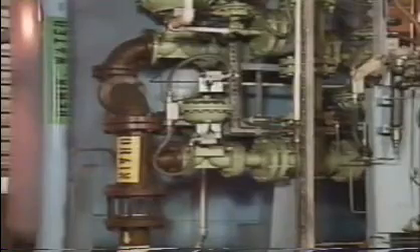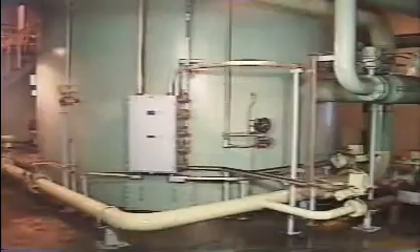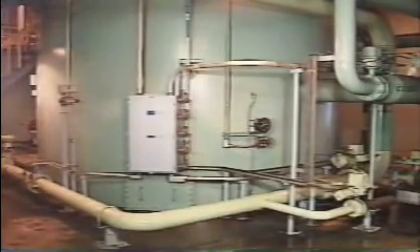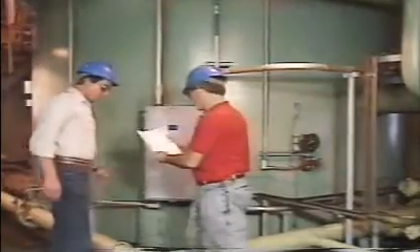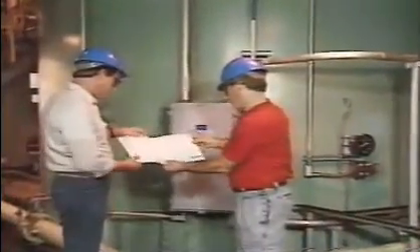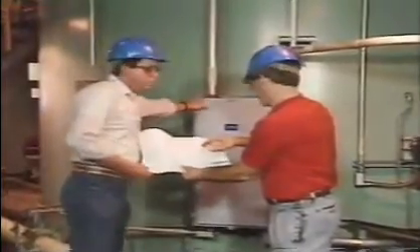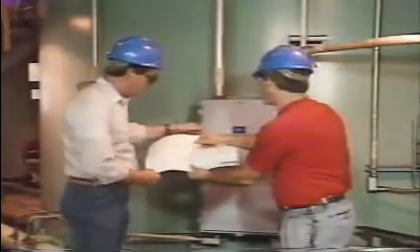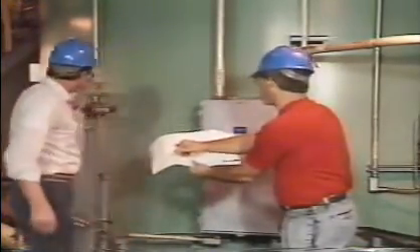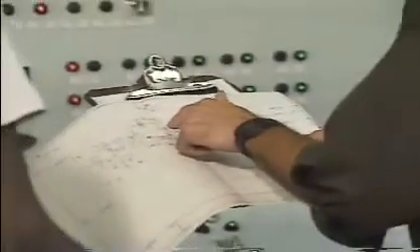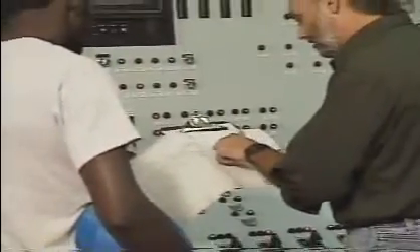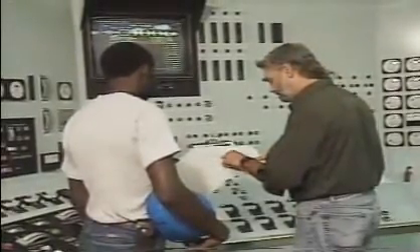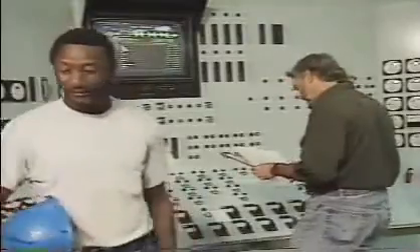Whatever the process at your facility, you've probably used instrumentation diagrams to help you understand the process system. P&IDs, that is, piping and instrument diagrams, or process instrumentation diagrams, show you each loop in the system, the instruments that comprise the loop, and identify all process variables. A P&ID gives you an overall picture of how the process functions. But sometimes you need more specific information about how instruments and devices are connected for power or communication. You can find this on an instrument loop diagram.